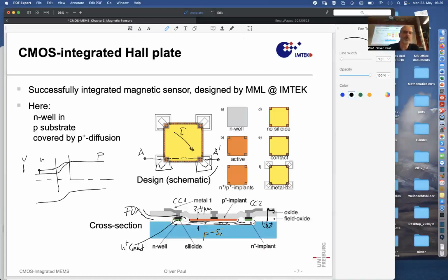And so you think, well, how do we get to these metal contacts? Of course, there is the intermetal dielectric with another hole up here, and then we have metal 2, M2. So if this is M1, and let's say this is also M1, then we have a second metallization that goes over metal 1 to reach this region, and of course this here needs to be also connected to some potential, to some part of the circuitry, either in metal 2 or metal 1. I don't know, somewhere there might be another transition to metal 2 also.